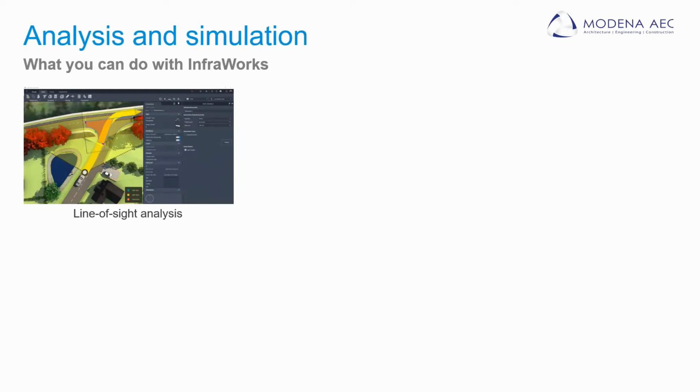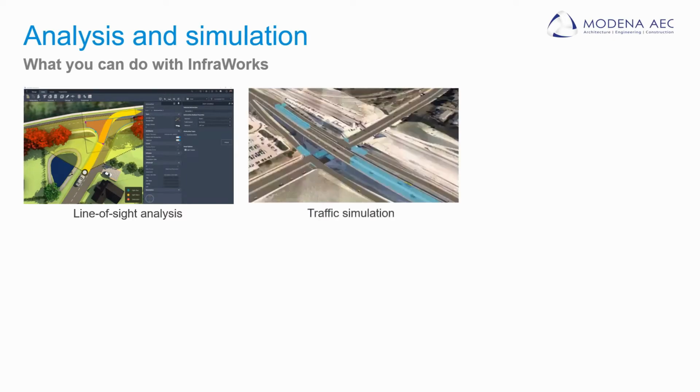So moving on to analysis and simulation. After moving through the stages of conceptual and contextual design, we can move on to analysis and simulation. I'll be quickly running through the different types of analysis available within Infraworks. Number one is line of sight analysis. This gives you color codes for site failure issues when looking at interchanges and intersections. You can do traffic simulations, which will give you an animation of the flow of traffic through your model, and you will be able to optimize your roads using that.